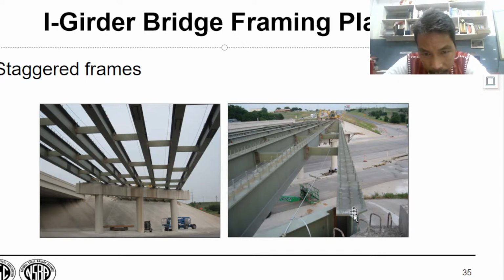Okay. Take a look at the plans. There are so many pins. Why? We will connect those pins to the reinforcement of the concrete decking. In our local dialect, abang na yan, nakaabang na. Abang yan para pag nilagyan natin ng reinforcement bars, dyan natin i-connect. And ipapalaman na rin natin yan sa concrete. Okay? So that is why we have this too many pins. There are protruding pins on the plans of the girders.